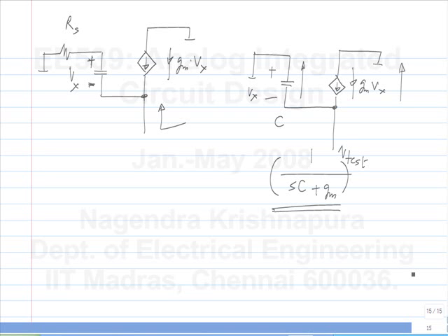Yeah, that is okay. One part of the impedance is simply the passive components that we have, right? So whatever components are here will appear in the impedance. I mean, the impedance of this branch will appear. But the more interesting part is we have a control source. So we can think of it as an admittance contributed by this branch and another by the control source. And the two will appear in parallel in the final picture. There will be some current flowing into this and some flowing into this, and the two will appear in parallel. And this, of course, will be simply a series RC combination. But the more interesting part is through Gm. What will that look like? Will that impedance increase with frequency, reduce with frequency, stay constant with frequency?